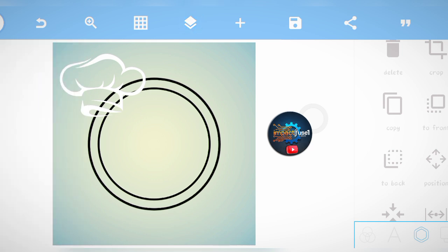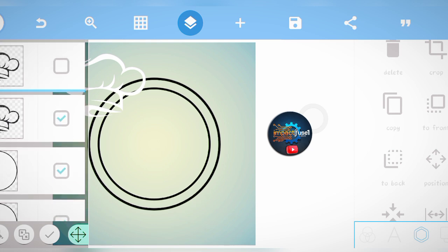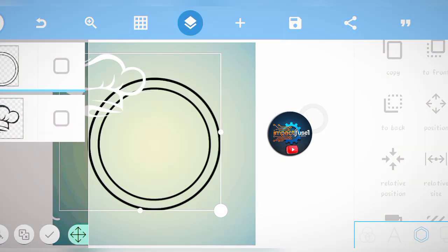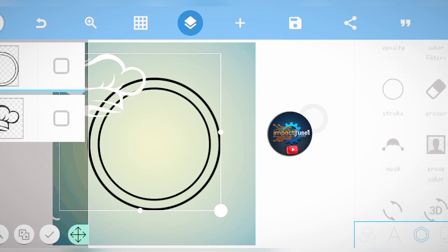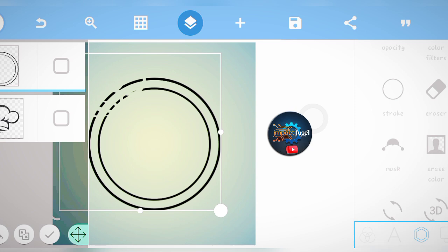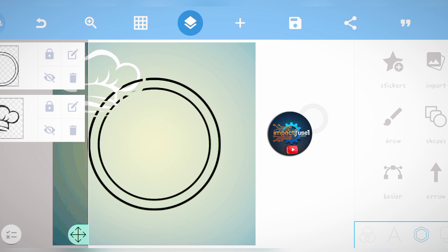Now what we need to do here is take all the shapes, 1, 2, 3, then do the merge. Please don't forget to select the one that you already hid. After I've done this, what next? Oh, let's look at it. We already understand. We just have to take erase color, which is going to get rid of this one. So I just increase the tolerance to 50 to 60 and validate, and that is okay. So now we are getting closer to the final point.